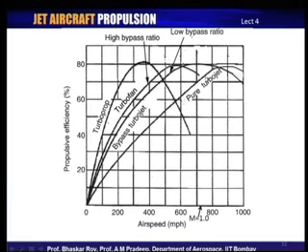And that is when the pure turbojets start coming up in their propulsive efficiency, and somewhere near Mach 2 the pure turbojet engines start becoming more and more competitive as opposed to the various versions of turbofan engine that we have talked about.